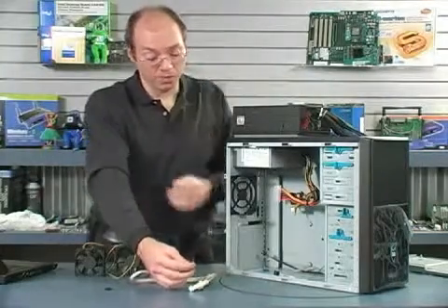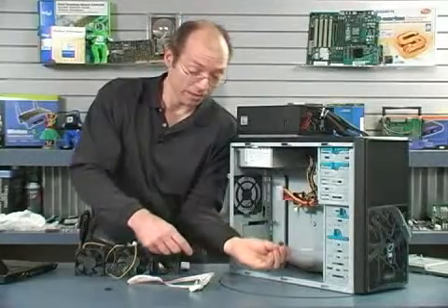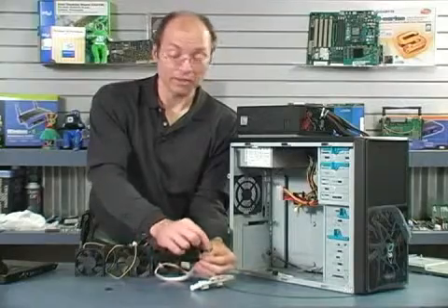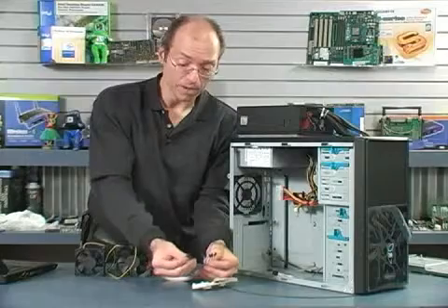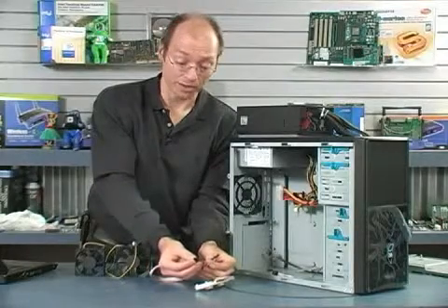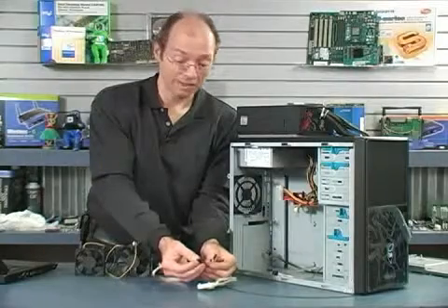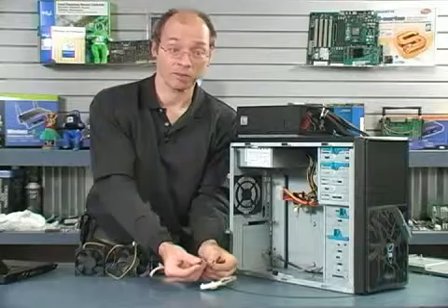So what I did with this case, which did not come with this connector on it, it came with an arrangement just like this. What I do is I take these individual 2-pin terminals off. I purchase a single 10-pin connector like this. You can buy this from a company called Frontex. That's frontx.com. They sell these individually. You can also buy them in bulk from any electronic supply house.